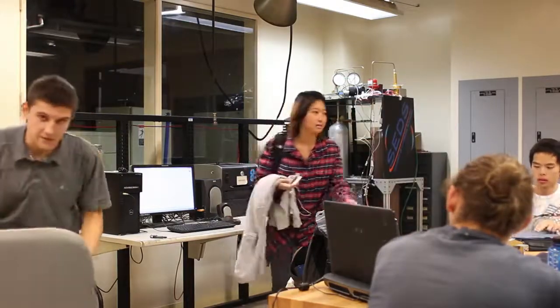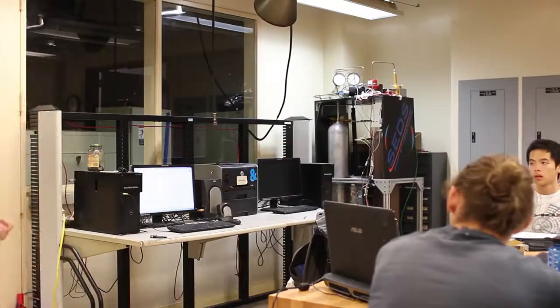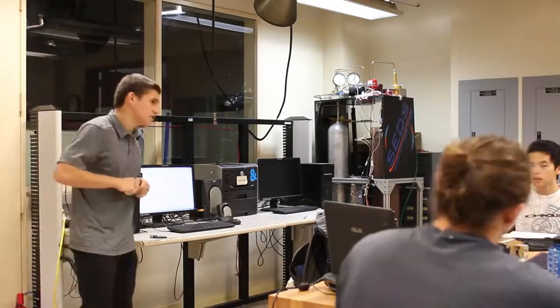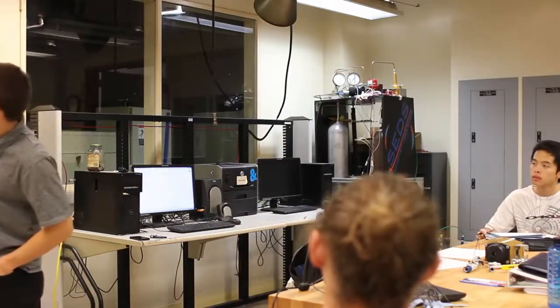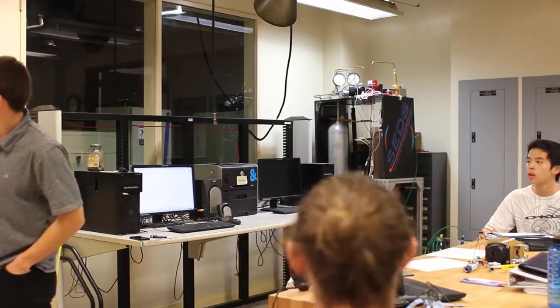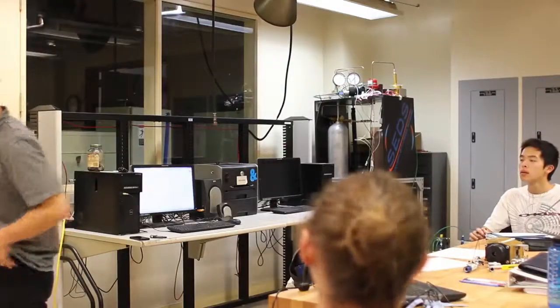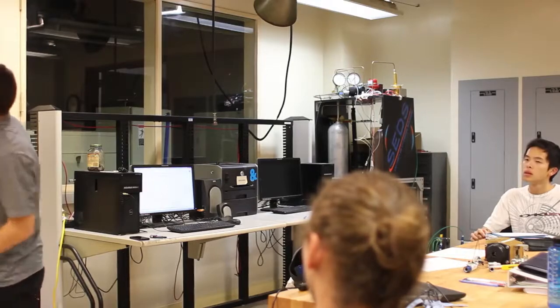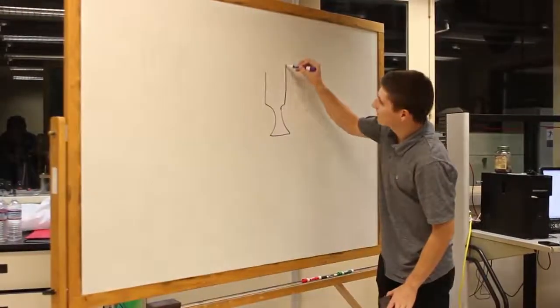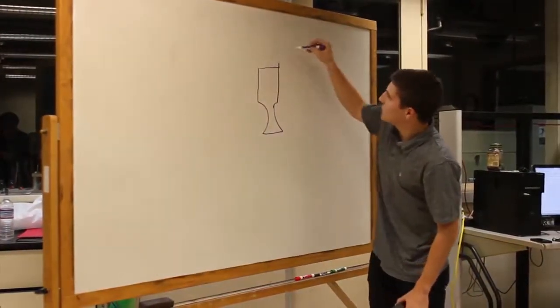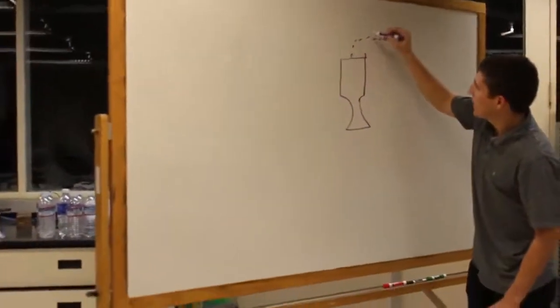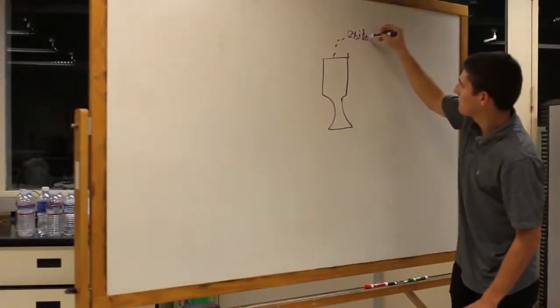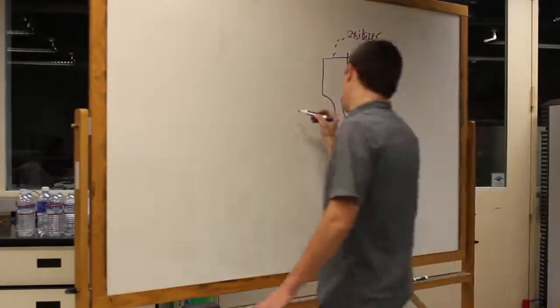So the very basics is how we're going to begin this. And what I would like to start with is just chemical energy and mechanical work. Basically, what we're going to be doing with liquid biprop engines is that you have a rocket engine that takes two components. And Edmund went over a little bit about this in the GDM, if you were there. So our engine feeds an oxidizer, and it feeds a fuel into the bottom.